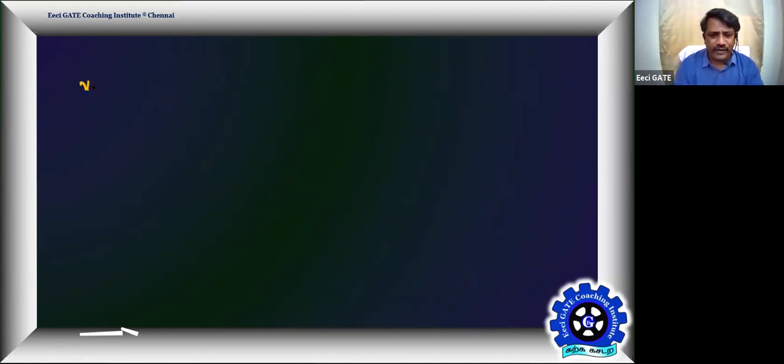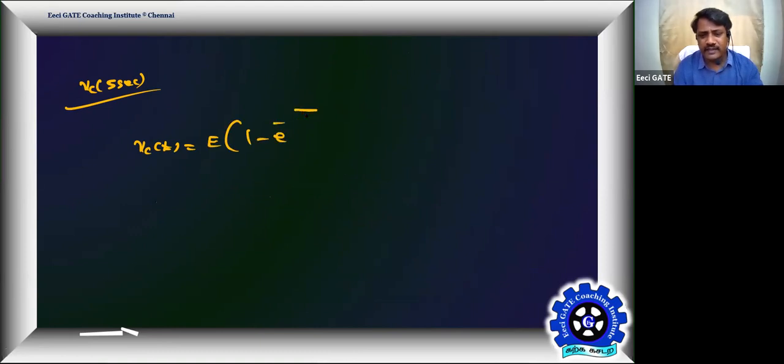We need to find out VC at 5 seconds. VC of t is E into 1 minus e power minus zeta omega n t by root of 1 minus zeta square into sine of omega d t plus theta, into u of t.